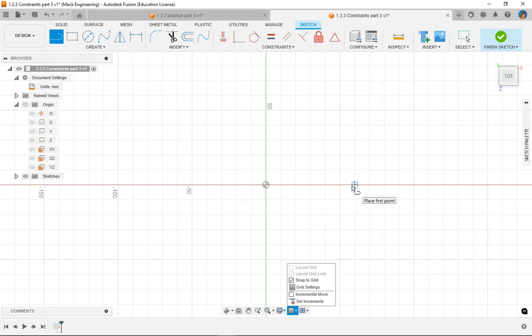And then I'm going to draw a line on my x-axis, and I'm going to cross over the origin point when I do this. Again, the actual dimensions and size of what I do is not as important. Step 5, we'll go in either 4 or 5. We go in and we force in the actual dimensions that we want. Right now, we're focused on the shape and the geometric constraints.